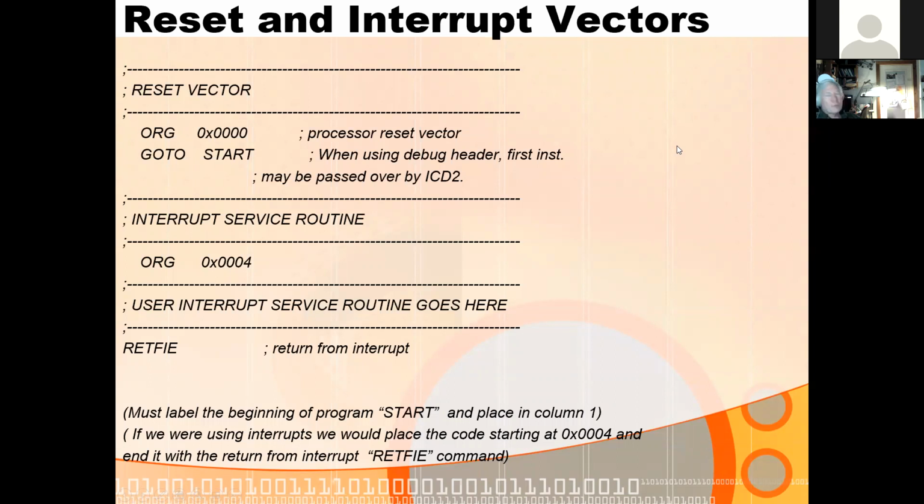Anytime you interrupt the standard execution, you have to flush the thing. But I don't think the interrupts take 2 instructions. I think they only take 1 to start executing. But that's a little different. But when you do a go-to statement, it takes 2 instruction cycles before you execute wherever you do the go-to statement to. Why do you think that would be?